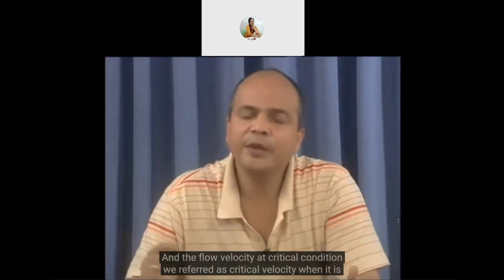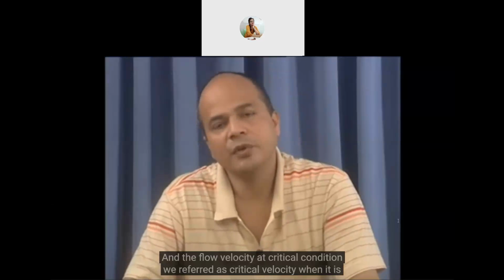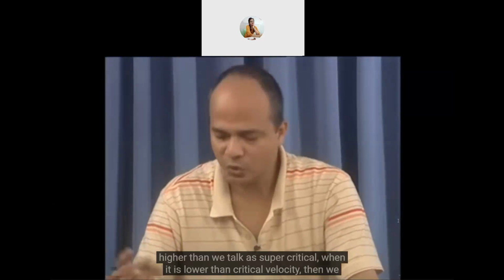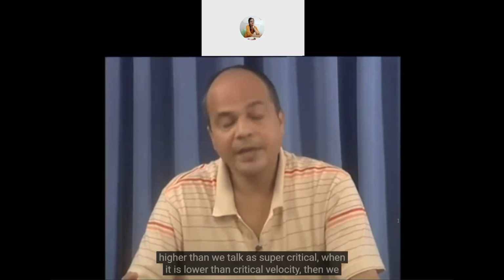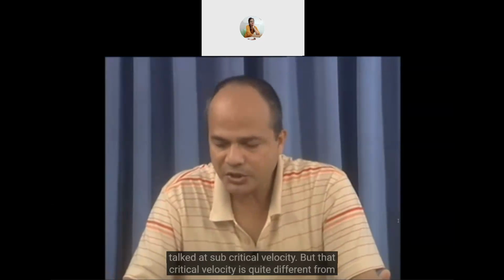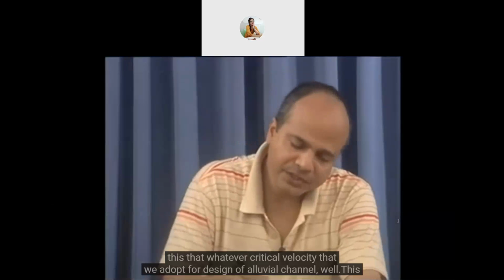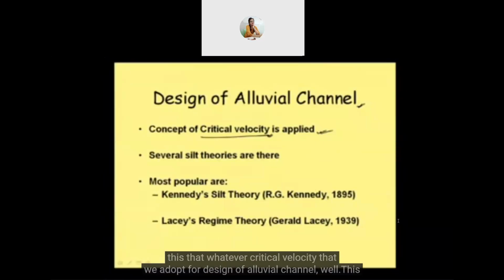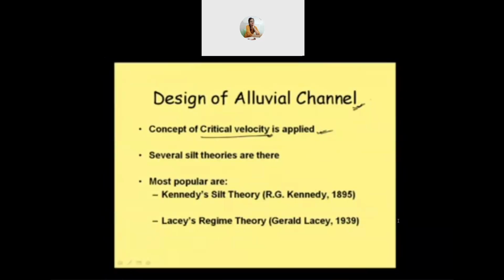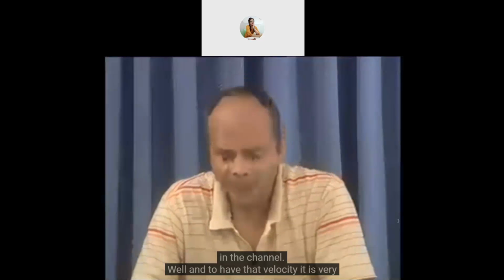And the flow velocity at critical condition we referred as critical velocity. When it is higher, then we talked as supercritical. When it is lower than critical velocity, then we talked it as subcritical velocity. But that critical velocity is quite different from this critical velocity that we adopt for design of alluvial channel. Well, this critical velocity is that velocity which will neither cause erosion nor cause deposition in the channel.